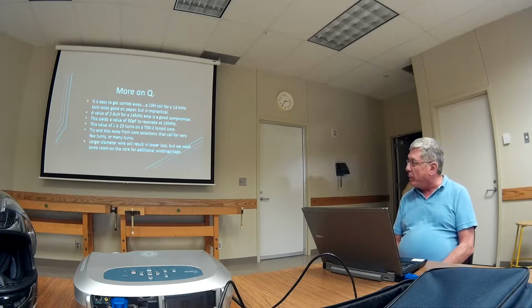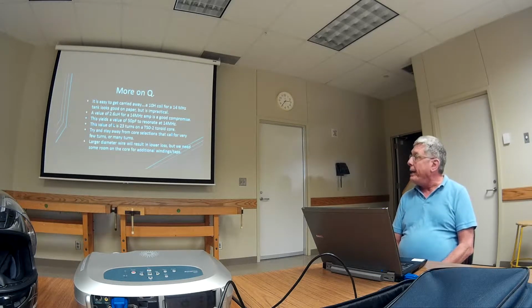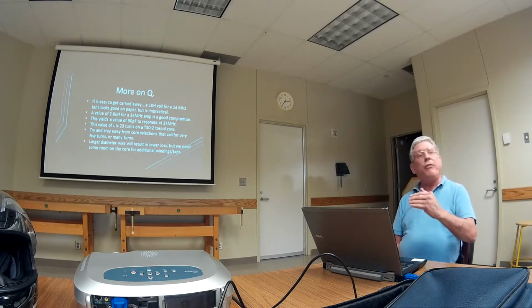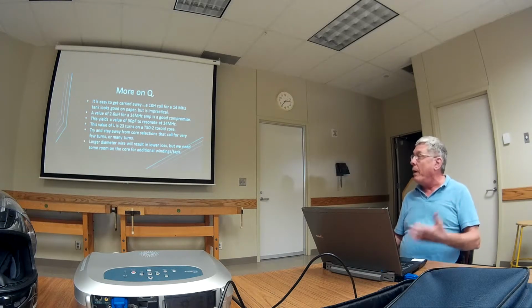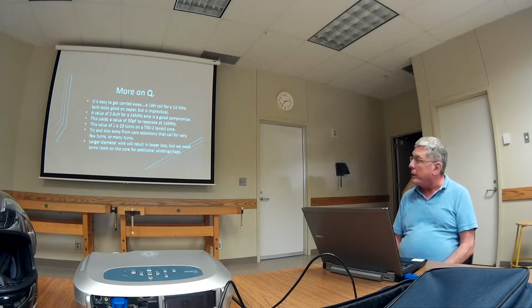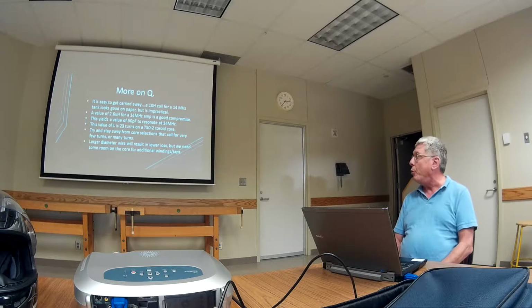A lot of my experiments around 14 meg tend to use something around a 2.6 microhenry coil, and that requires about 50 picofarads to resonate at 14 meg. Below that 50 pF value, the stray capacitance becomes most of your capacitance, and you have a hard time tuning your circuit. So I try to stay around these values. Depending on what calculator you use, that's either 23 or 24 turns on the T50-2 toroid core.